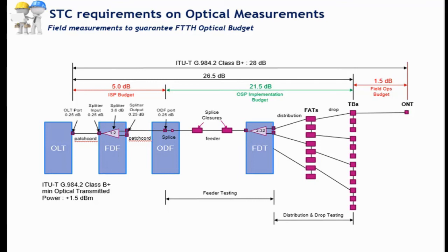Because we are also allowing the optical absolute power test measured at the TVs, the reference at the TV level is minus 25 dBm absolute power, and knowing that the OLT transmitted power is in the range of plus 1.5 dBm, if we add plus 1.5 dBm to minus 26.5 dBs of attenuation at the TV box, the minimum optical power that we can measure is minus 25 dBm.